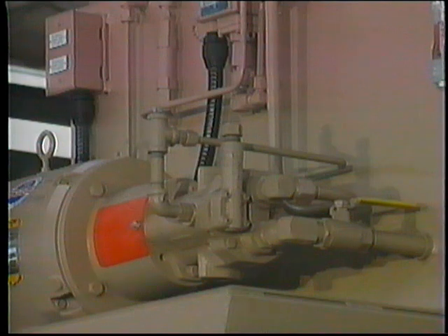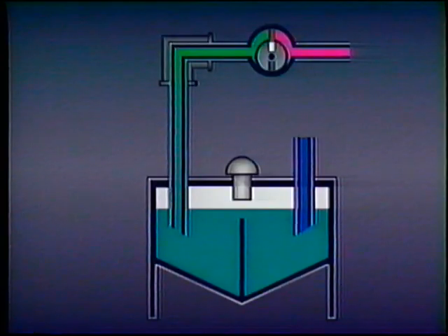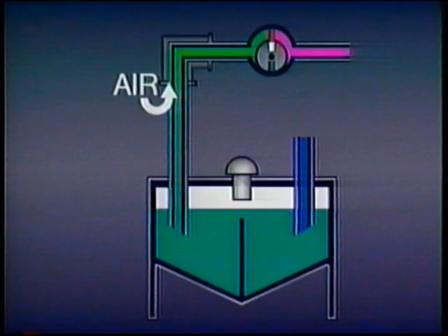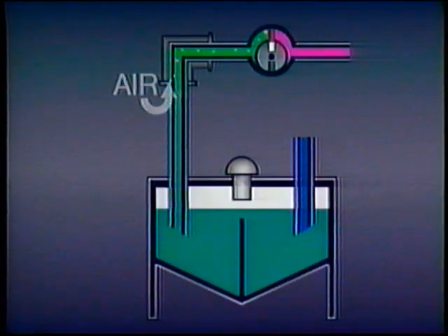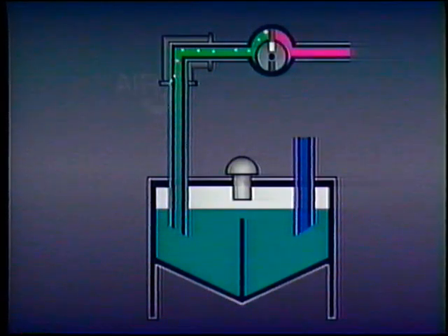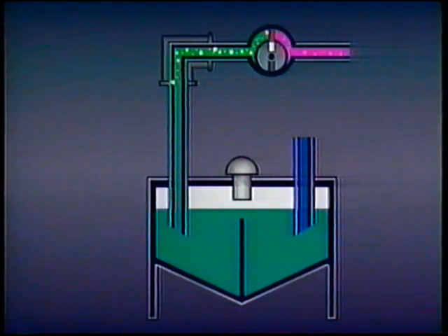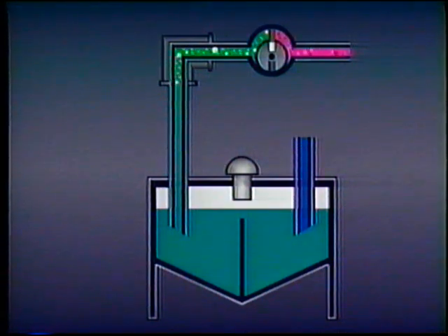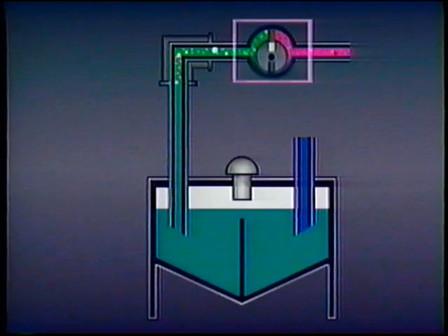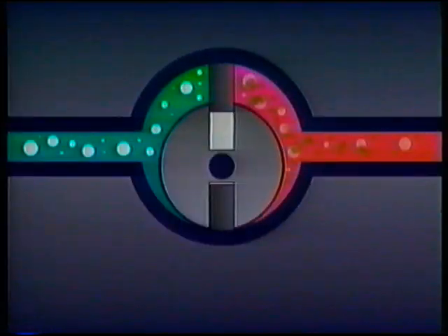However, oxidation inhibitors have little effect when oxidation occurs at the outlet side of a hydraulic pump. Oxidation in the pump happens when the air is allowed to enter the suction line through a leak or by excessive churning of the oil in the reservoir. In either case, the air forms bubbles which collapse when they are subjected to the high pressure at the pump outlet. This not only oxidizes the oil, but the collapsing bubbles create extremely high temperatures which can actually fry the